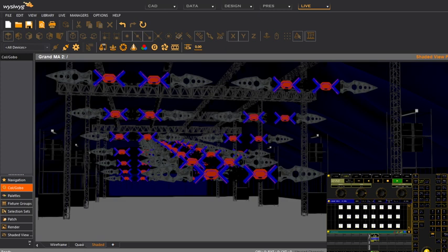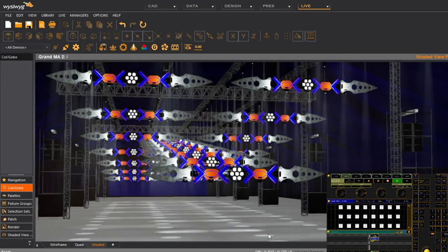Alright, let's take another position. Let's go into grandMA. Alessandro, consider that you have your lights in a position. Can you set a marker in such a way that if you move the trusses, the lights remain in that position? How exactly do you mean that? So the way it works here, the lights that are hanging on the objects, which I can highlight, are also assigned to the frame, so they will also move with the frame. So it will all stay connected together.